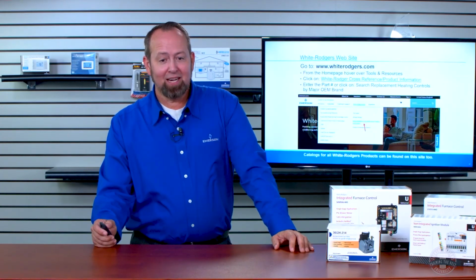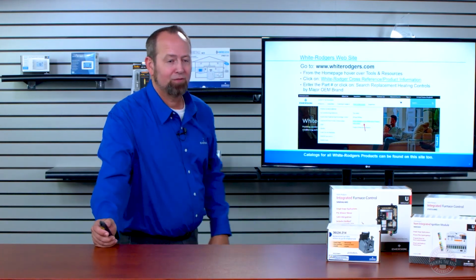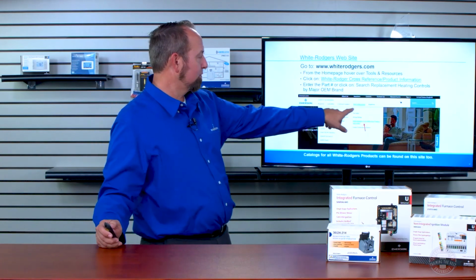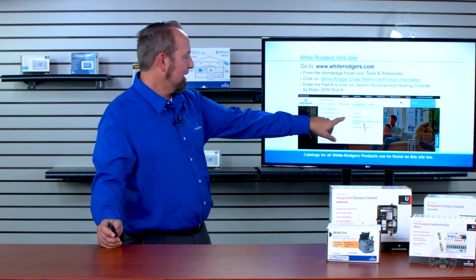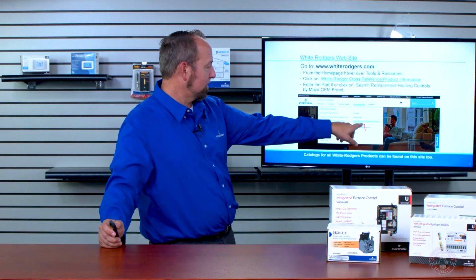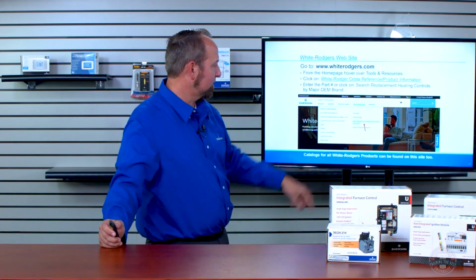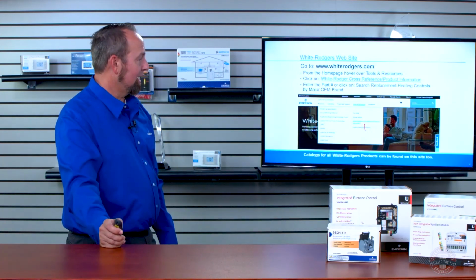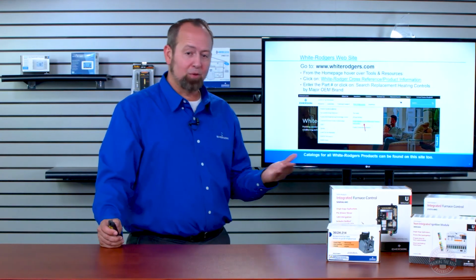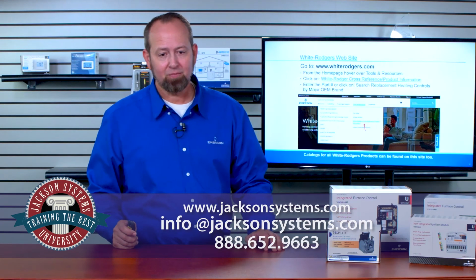And then the website, if you just simply go to www.whiterogers.com, there is a spot from the home page. You can hover over tools and resources, and in there it's going to say White Rogers cross-reference product information. You click on that, and there you can enter your part number just like you would on your app, and that's going to be able to show you exactly what you need for the universal replacement.